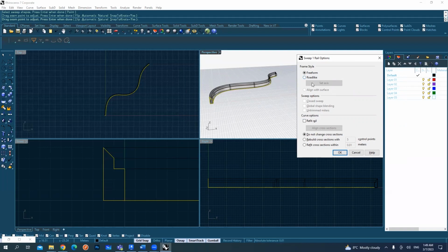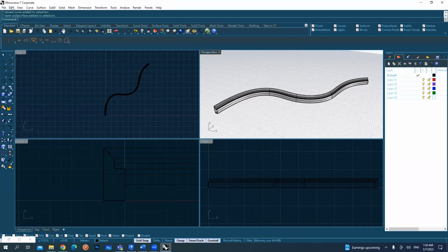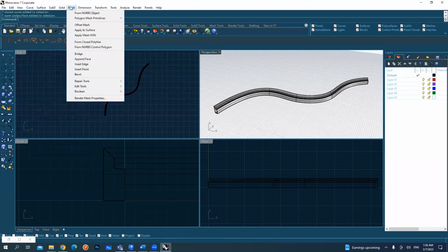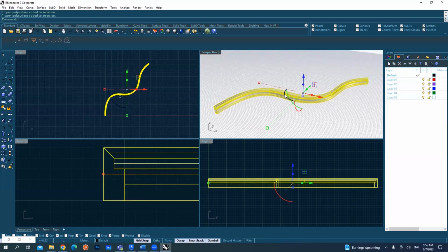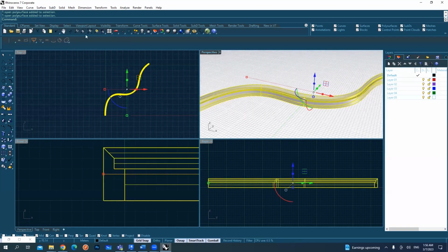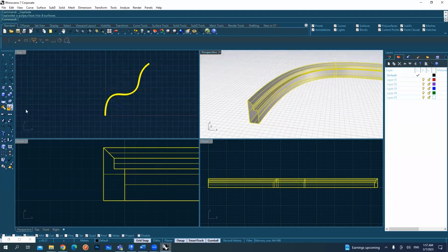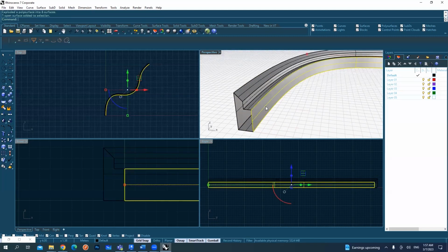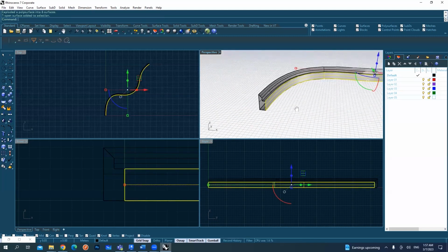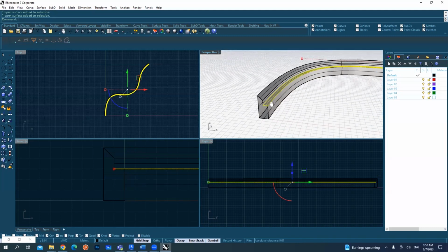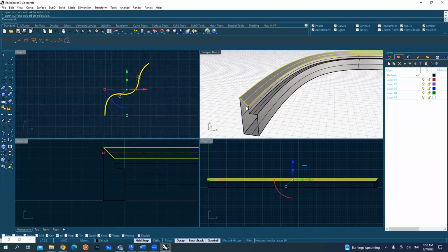So if you want to, I don't know, rebuild it with a different value. The surfaces that Rhino uses are different from mesh. So now the things that we are creating, if we select them, you can see here it's a polysurface, which is like a group of surfaces. If we explode them, I exploded them now, this one is one surface with this face. This face is another surface. This one is different. This one is different.